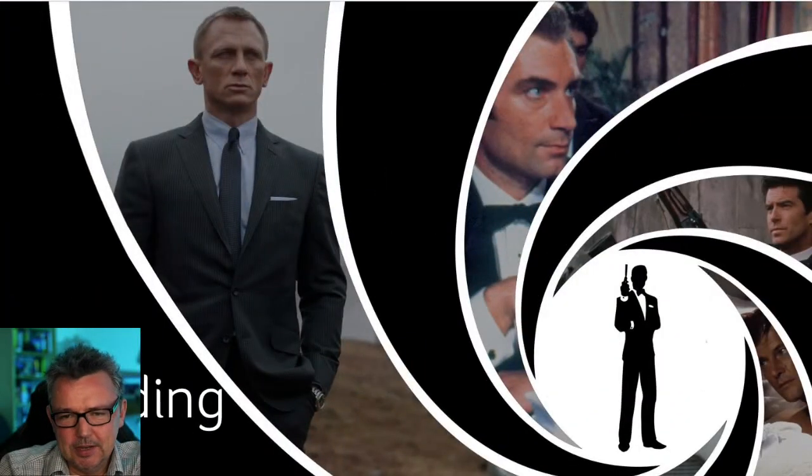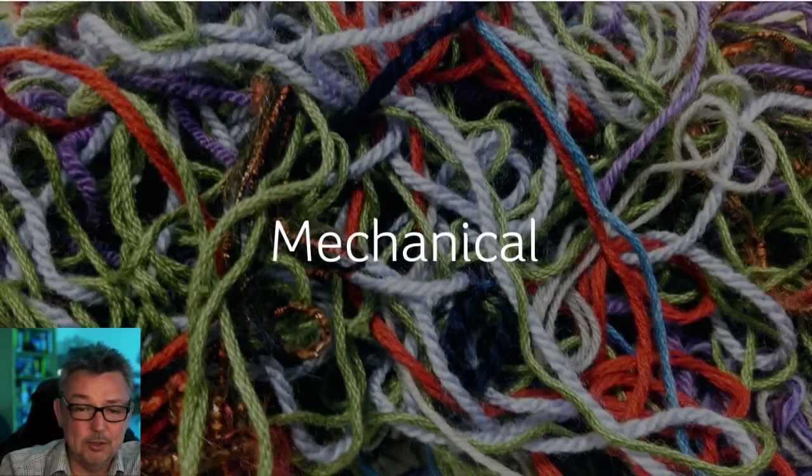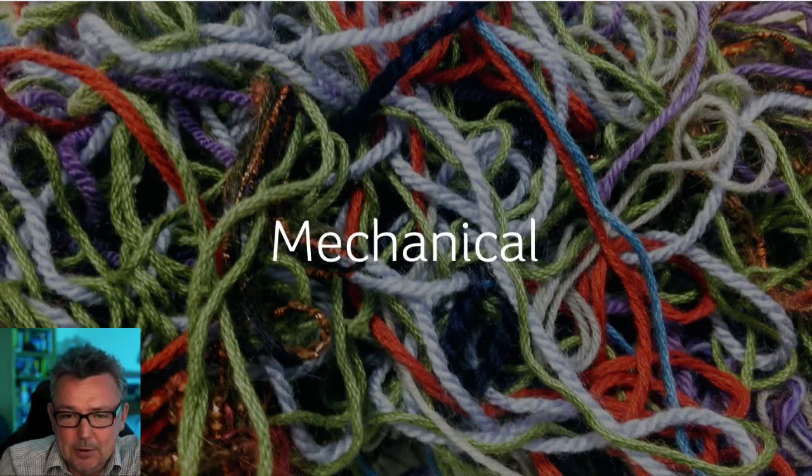So in terms of bonding, a couple of examples here as well. Mechanical bonding, where you basically twist fibres together through mechanical action. Needle punching with barbed needles is one way of doing it. Hydroentanglement with little water needles, effectively little high pressure jets of water to twist the fibres around each other, is a popular technique known in America as spun lace.